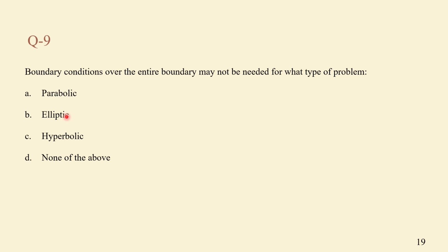as I mentioned before, the governing equations in CFD are partial differential equations. So what we should know is how to solve these partial differential equations. Before that, we need to identify the class of the partial differential equations. For that purpose, partial differential equations are divided into three types, parabolic, elliptic and hyperbolic, and also a mixed type.